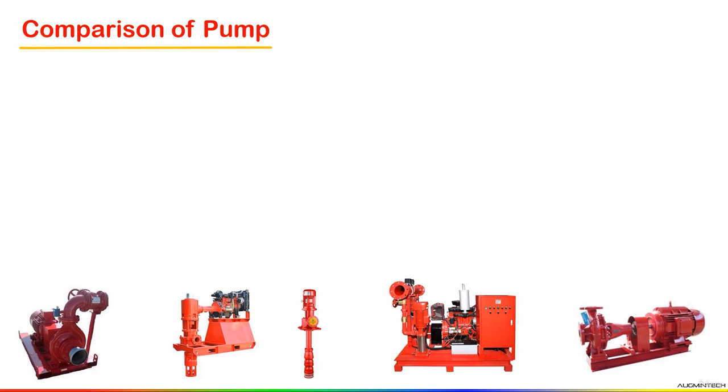Both horizontal split case pump and end suction pump come under which category? Horizontal centrifugal pump category only. And vertical turbine pump and vertical inline pump, both come under the vertical centrifugal pump category. If I compare horizontal centrifugal pump and vertical centrifugal pump, remember in a horizontal centrifugal pump the position of the shaft is horizontal, but in a vertical centrifugal pump the position of the shaft is vertical.